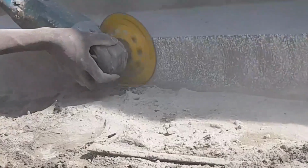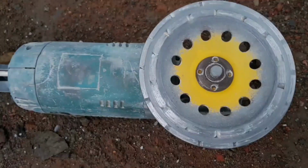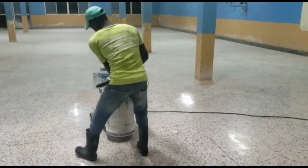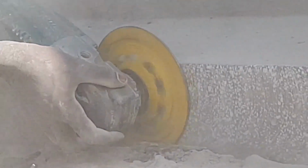The first phase under the grinding process is using the diamond stone or this diamond wheel. It's called diamond because this surface covering has a real diamond coat here. When using a machine like this one, we use a diamond stone for grinding, then for the angle grinder we use this diamond wheel in the first phase.